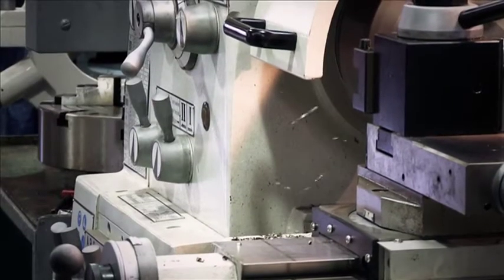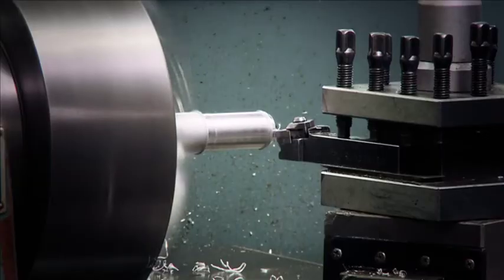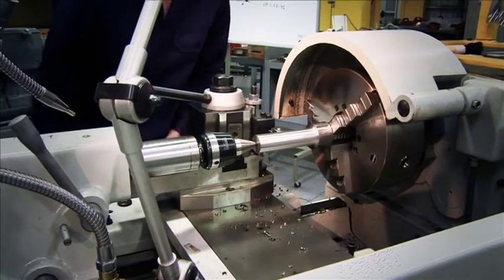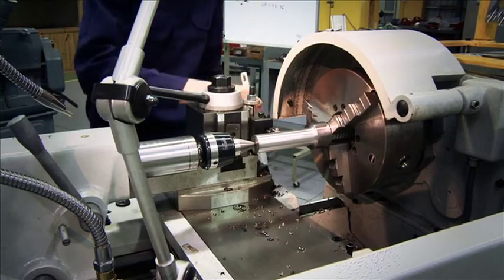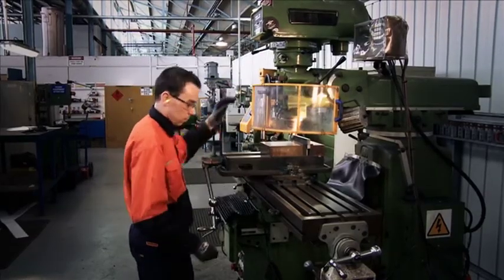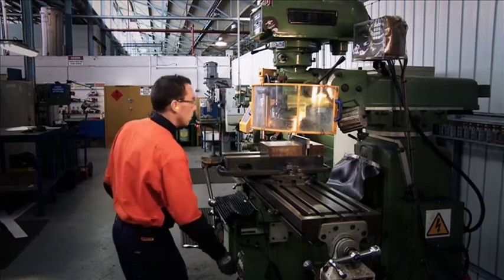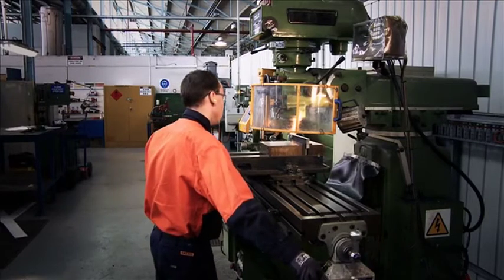Using lathes, milling machines and drills can produce flying debris called swarf, which is extremely sharp. Never try to remove swarf with your hands. There are tools available to safely remove swarf. Lacerations can lead to serious injury and even loss of limb function, so don't rush or take shortcuts that could cost you your career.